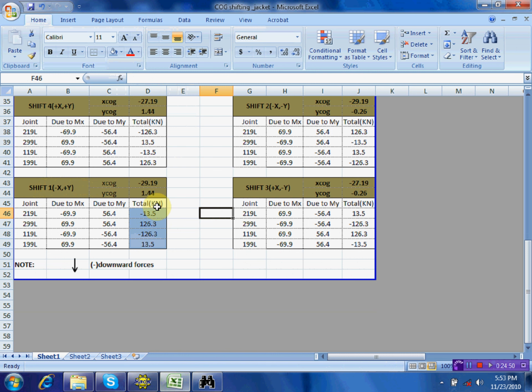So, in order to compensate that one, if you shift this to the left, your moment on Y should be to the right, MY, to compensate this one, because it will be rotated in the left. Your weight is already here. So you move that one, so you apply MY. If you put your load on that direction, what is the location of your MX? Opposite, always opposite. If you move in that direction, clockwise, it should be here, right? MX, moment about X, this should be the applied moment.